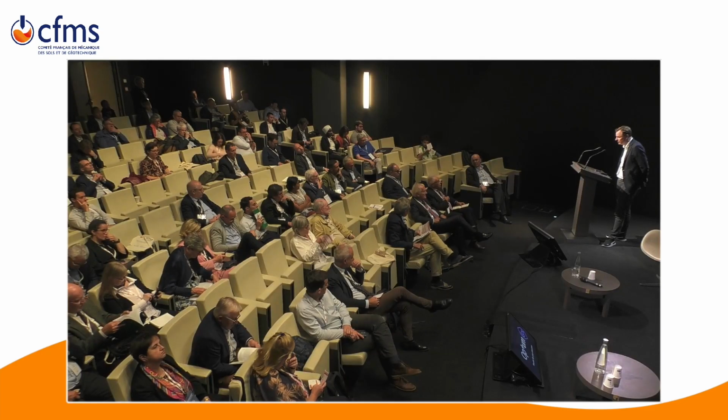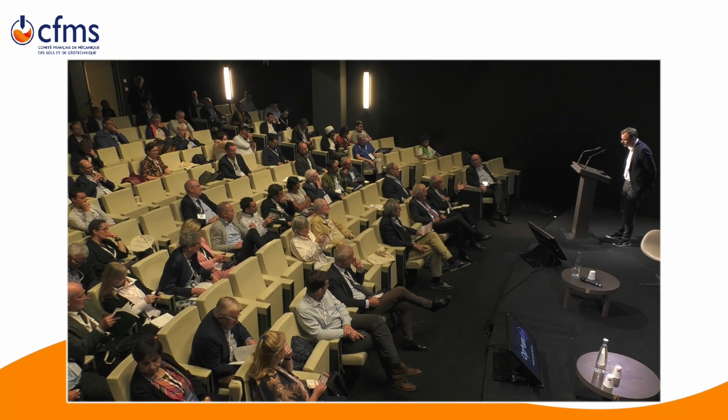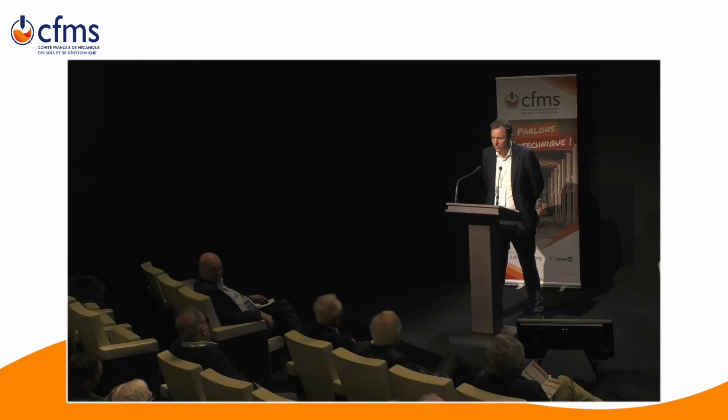The second question is about calculating settlement, because in that case you should know the loading path. Since you are working in elastoplasticity, what kind of loading path do you impose? We impose whatever loading path. That's up to you. You impose the loads as boundary conditions, and then your equilibrium equations, your constitutive model, and so on take care of the rest, as in conventional FE.